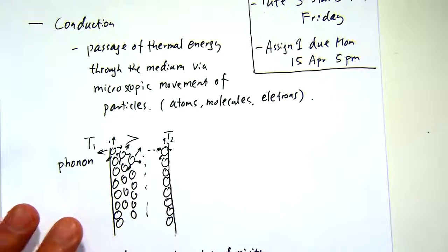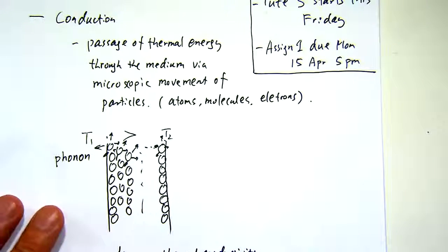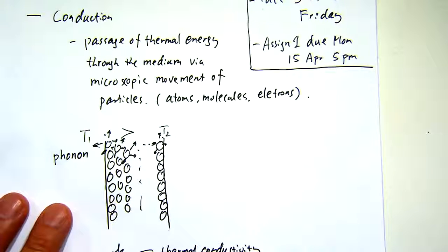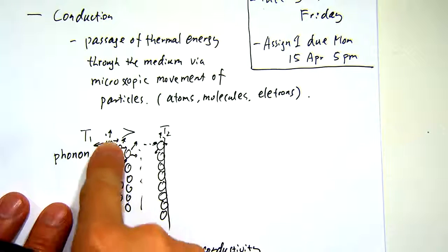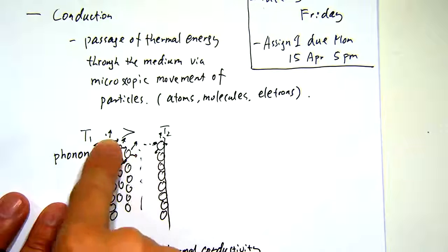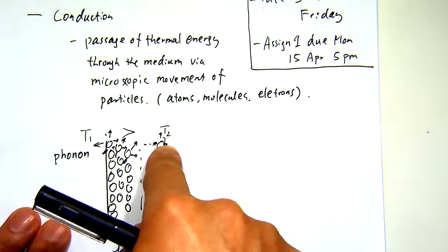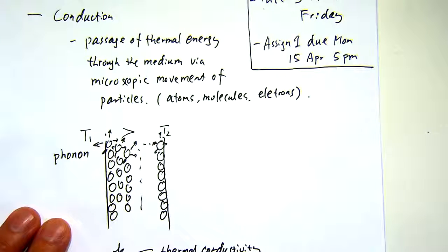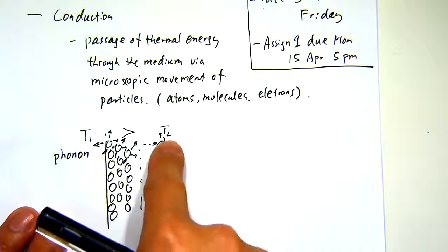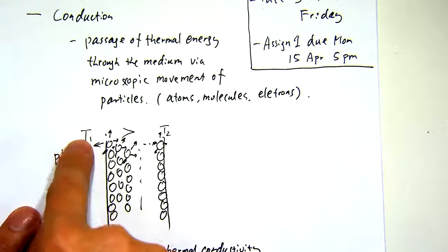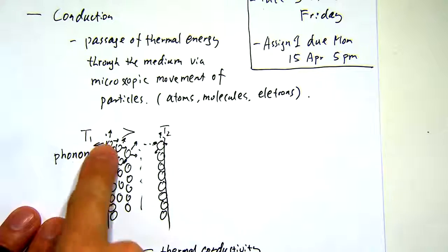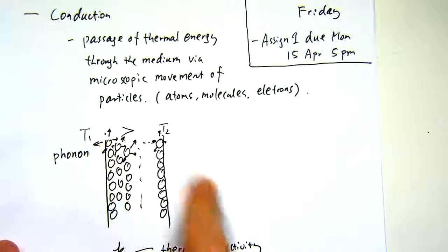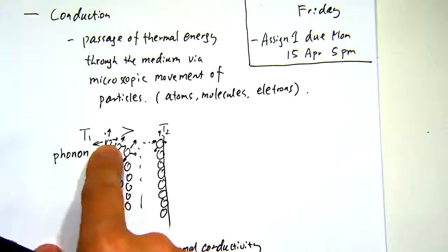So thermal conductivity, you can consider that's something to describe how effectively, how efficiently the energy can be transferred across a medium. If the energy loss is less, which means the energy can be more effectively transferred to the other side, right? So in this case, K is a large value, higher thermal conductivity, and in that case, the temperature of T2 and T1 will be relatively close if we consider the input energy as the same. For the same amount of input energy, with a larger K, T2 will be closer to T1.